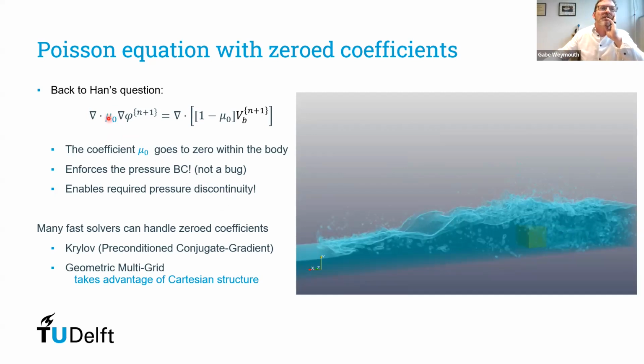The fact that we turn this off in terms of the momentum equation means that we can have pressures with a giant jump across a small interface, and we don't get some giant force applied to the fluid there. We don't want a giant force. We want there to be the right amount of force on one side and the right amount of force on the other side. And then we want the boundary condition for the velocity to take over inside the body. So this isn't a bug, it's a feature. And it doesn't really matter in terms of the solver.